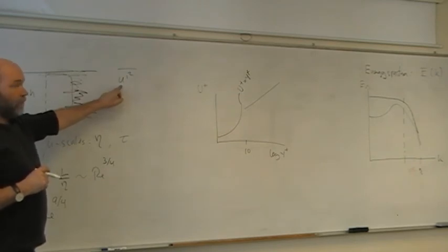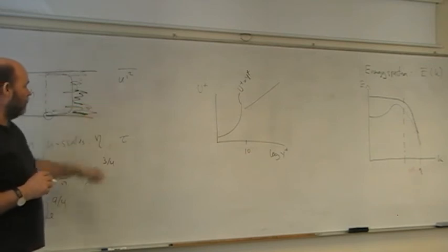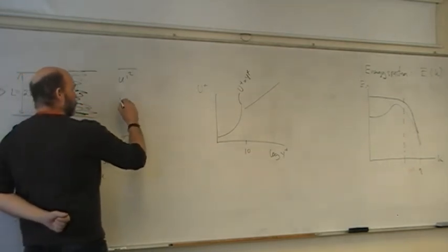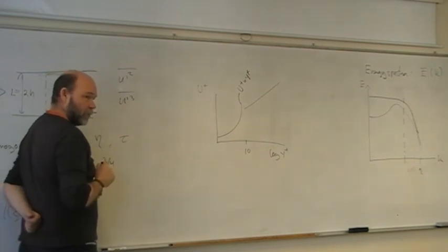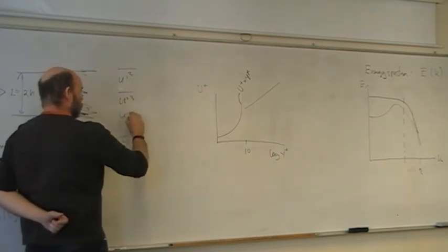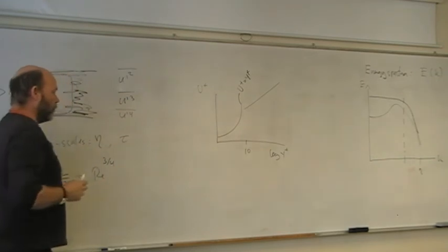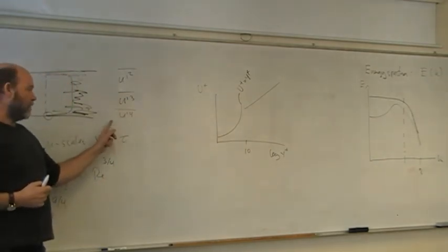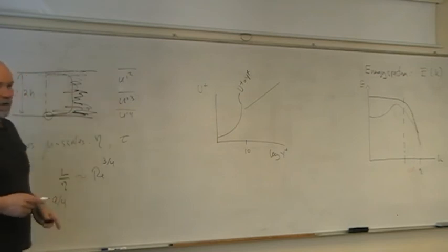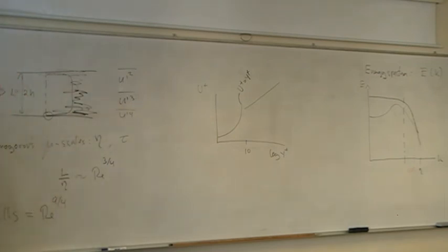But of course you need the Reynolds stresses to define it. And then you're looking into u prime cubed. Now you're talking problems. Not to mention u prime to the power of 4. These are extremely sensitive, more and more sensitive to errors. So here you can really tell whether you have done a good simulation or not. But we will come back to it.